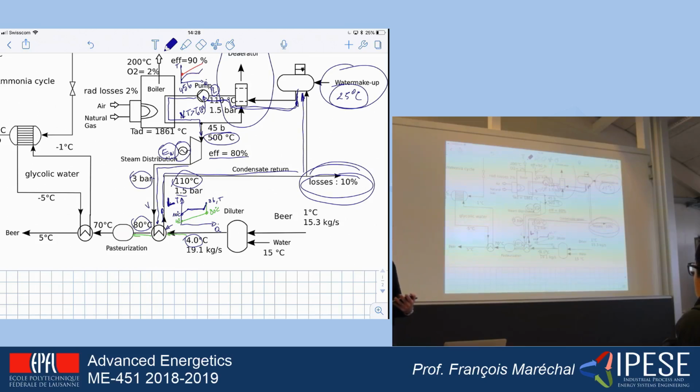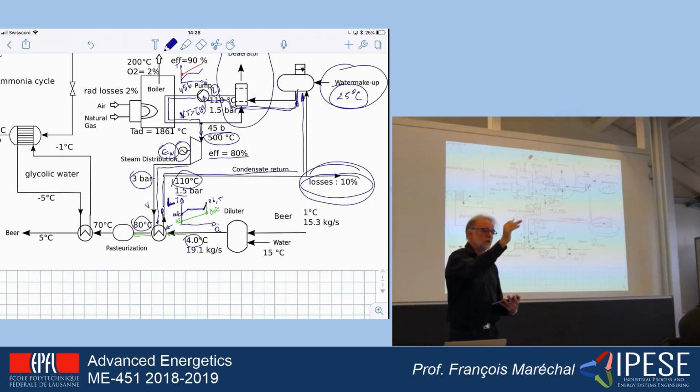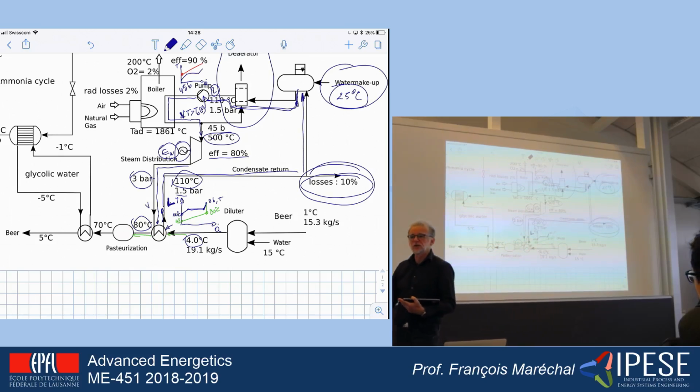So if you increase the temperature, the pressure being constant, then the volume is going to increase, right? And as the volume is going to increase, and the gas is much lighter than the liquid, it is going to take a lot of room in the pipe. Okay, and if you have a bubble of gas that is then taking more and more room in the pipe, it is going to try to take more place, and it will push the liquid out. Okay, and this is going to create problems in the heat exchangers and everywhere.